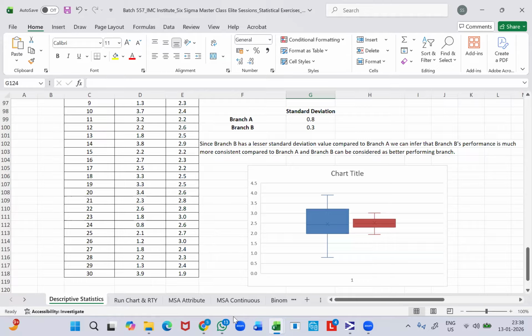In discrete data measurement system analysis, the quality inspectors alone will form part of the measurement system. The discrete measurement system analysis is also referred to as attribute agreement analysis, or attribute R&R. We will conduct the exercise by considering a minimum of 30 sample units.